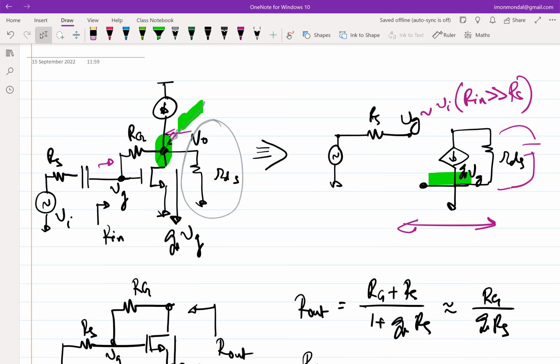There are two ways of approaching a problem. You can do brute force and figure out the exact expression. You will get a nice exact expression. But the thing is that sometimes in any design, you lose the crux of the problem in the detail. What I am trying to motivate here is that if you know exactly where the current has to flow through, all you need to know is the impedance of various directions. If you know the dominant impedance, I mean the lowest impedance path, the current will always try to escape in that direction.